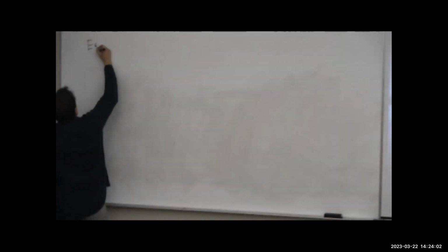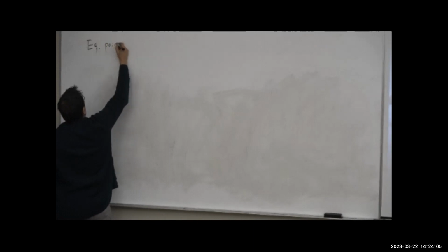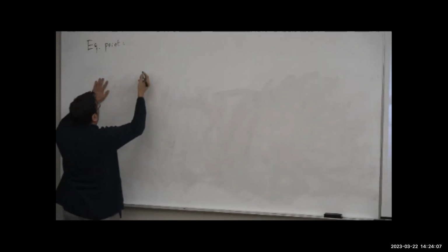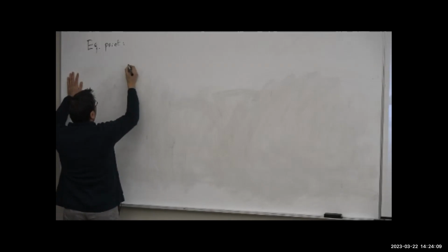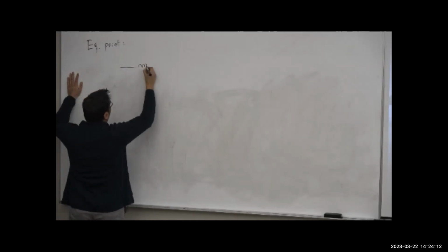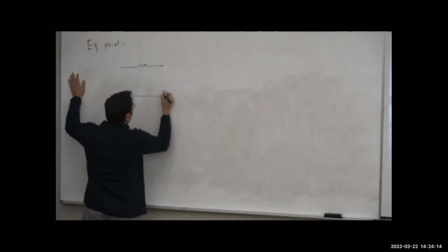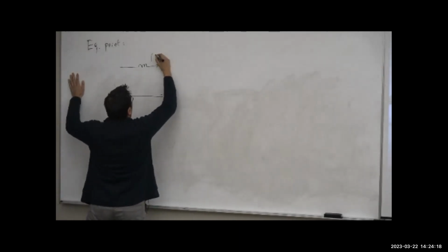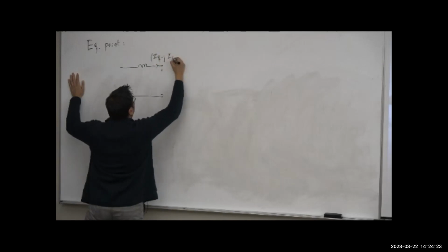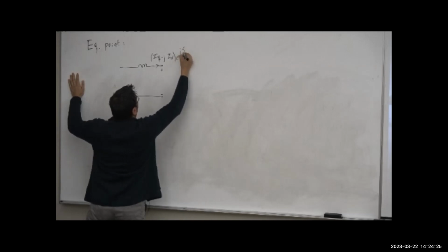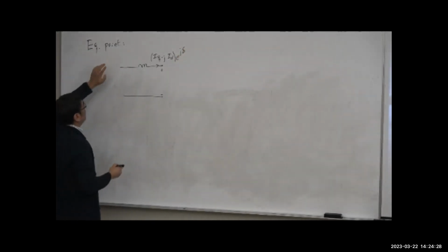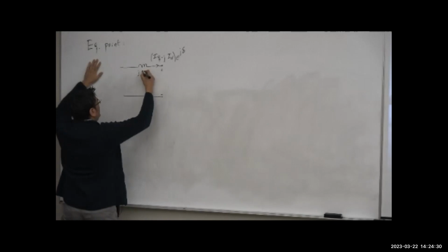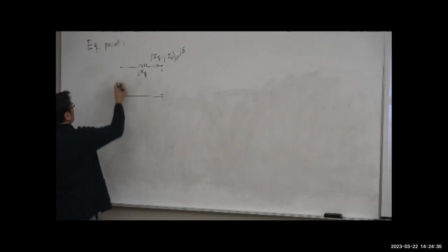So the first step is to find the equilibrium point of the system. So we will have here the model of the machine. This is the voltage at the terminal. This is the current in the machine. And because we're trying to find the equilibrium point, the model needs to be the steady state model that considers here the quadrature reactance.